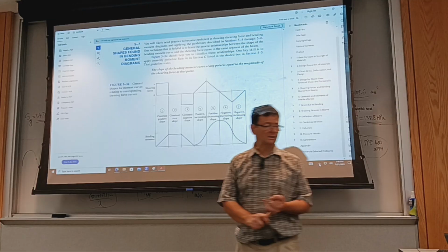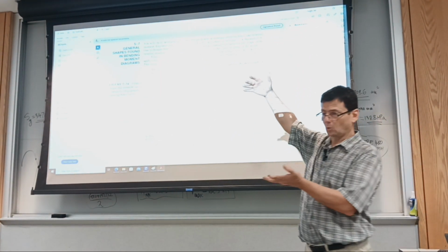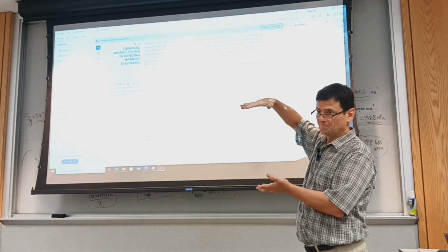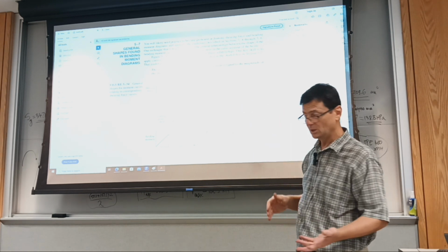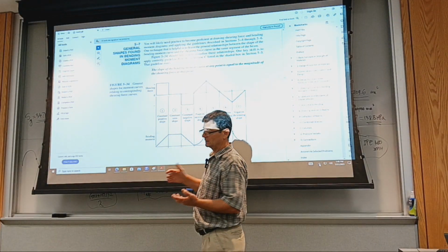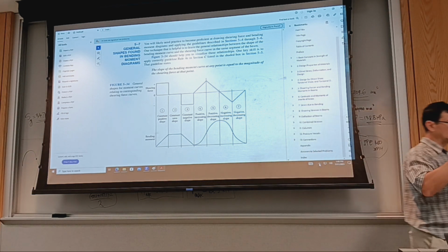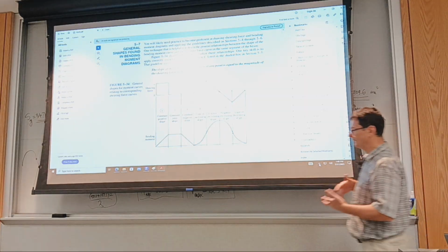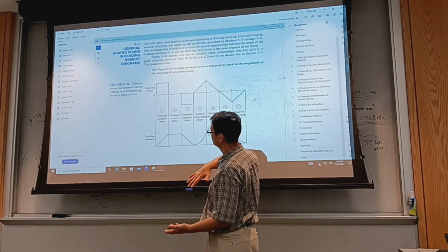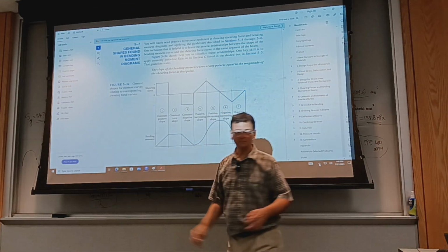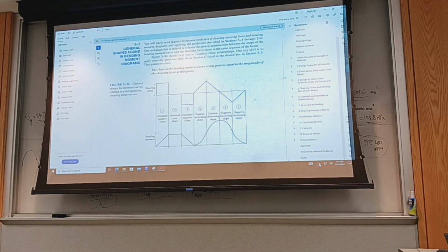And as we study deflection in the next chapter, you will see they correlate nicely. So the distributed load gives you information on the slope of the shear diagram. The shear diagram tells you the moment diagram, because the derivative of moment gets you shear, and then through integration, deflection. The derivative of deflection gets you slope, and the derivative of slope gives you moment.